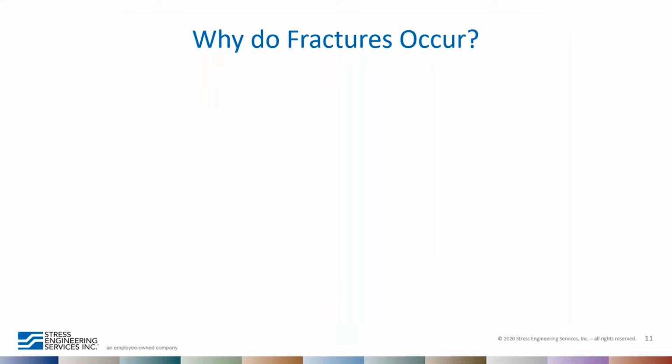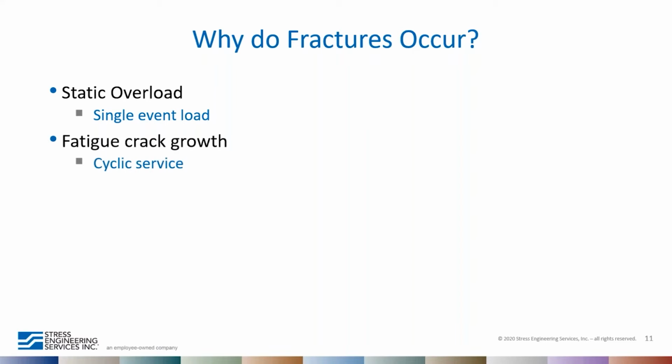Okay, so cases like this certainly provide a general motivation for why the industry needs to understand fracture mechanics, and so the question of why fractures occur. In general, fractures occur for a number of reasons. You may have a static load event. This is a single load event, maybe a hydro test or an overload. Usually it can be influenced by the presence of a stress concentration factor, which leads then to a failure.